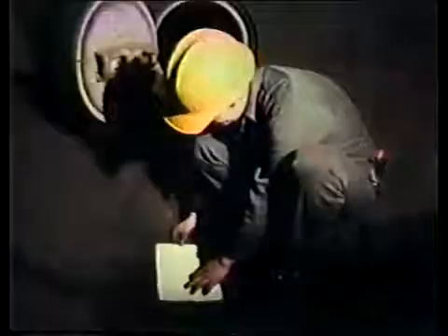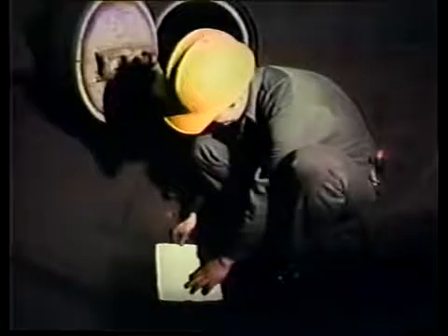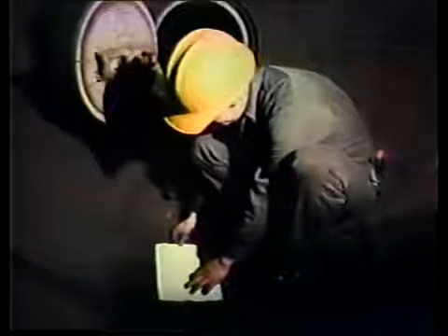Any oil in the boiler must be removed before the boiler is returned to service. Putting a boiler back in service when oil contamination is present can cause major damage to the boiler. The contaminated oil will form a coating on the inside of the boiler that'll cause overheating of the boiler metal. To find oil contamination, run a piece of paper along the component's internal surface.